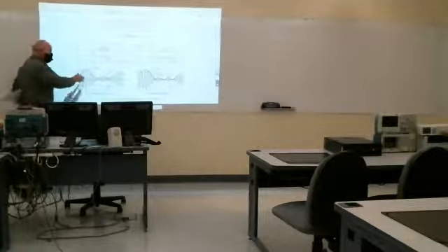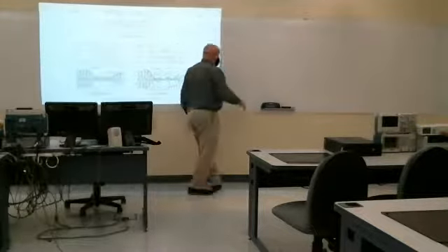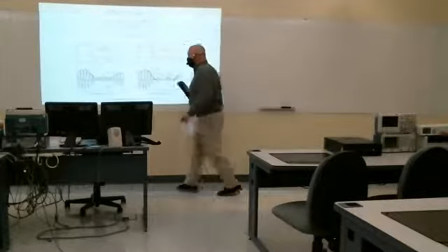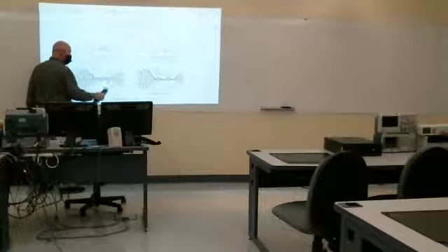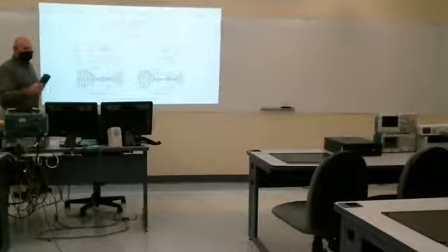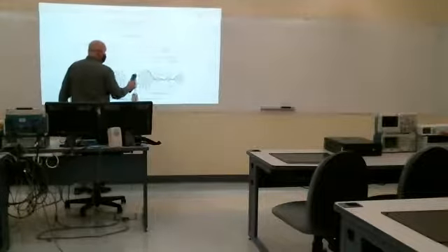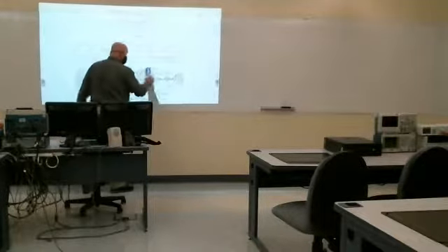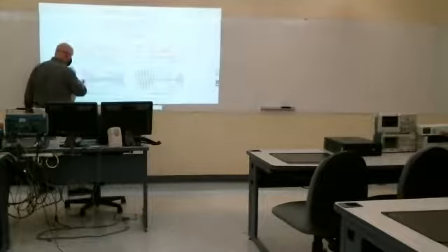So this is why we have that requirement. The reason is we're going to use an envelope detector that just follows the peaks to recover our low frequency signal. And if this condition isn't met at the transmitter, then we get a distorted version of our message signal.